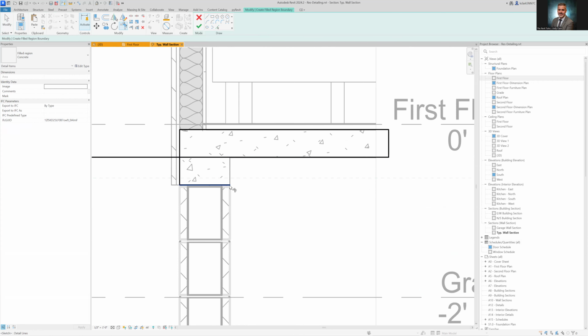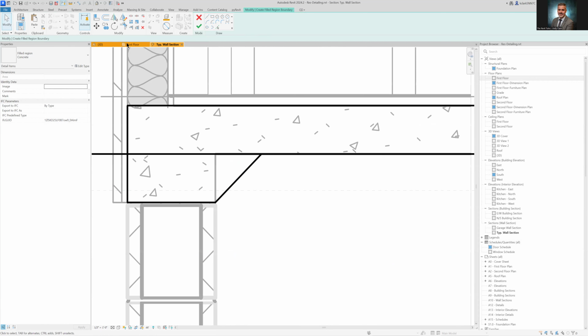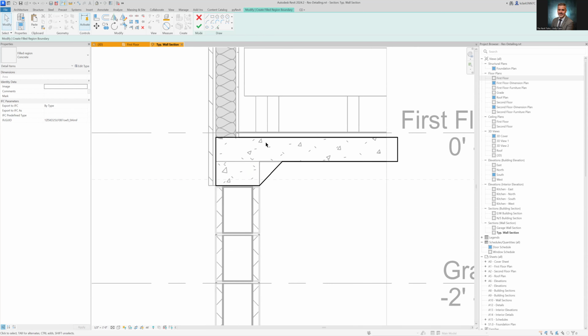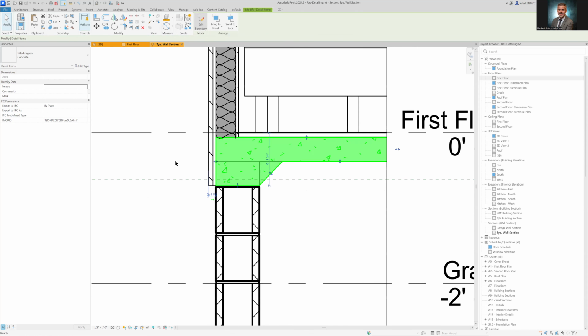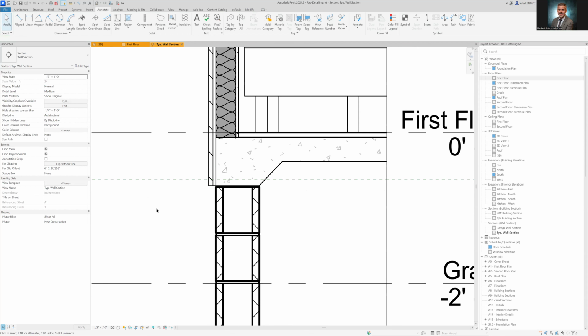And then this one's gonna be part of a 45-degree angle that I'm gonna put in. So I'm gonna hit my straight line tool. I'm gonna start here at the end, and Revit's letting me know where those degrees of angles are, which is nice. I'm gonna use that corner trim again, pick there and there. Okay, so this is gonna act like a mask. It's gonna cover this over for me. I'm gonna finish it. And when I click away, notice it's cleaned that up nicely.